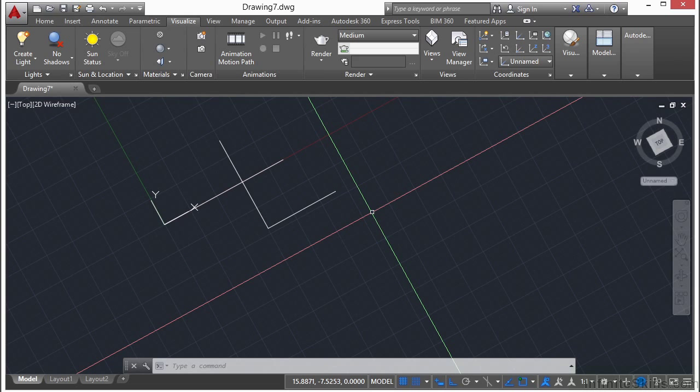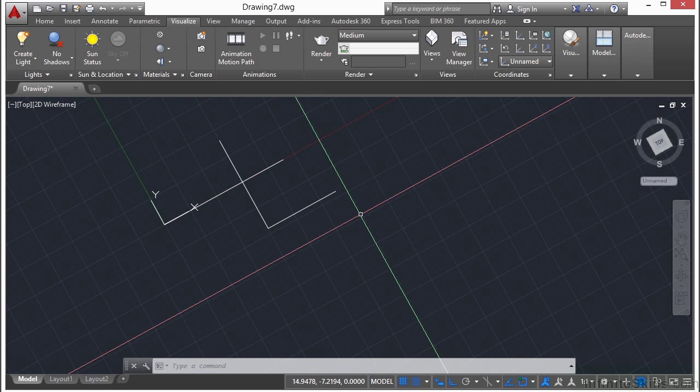Now, when you work in 3D, the UCS is key. There's a function called the dynamic UCS feature that will automatically change your UCS to match the face of an object, allowing you to draw on that same plane as the object is selected. That's probably one of the most commonly used cases of changing your user coordinate system, when you're working in 3D. Now, that's getting a little bit heavy, of course, for this course, but it's hard enough to keep track of just 2 axes, much less 3 or 4 or 5 different coordinate systems that you might want to use. So we're going to try to keep it more simple for you in this introduction.